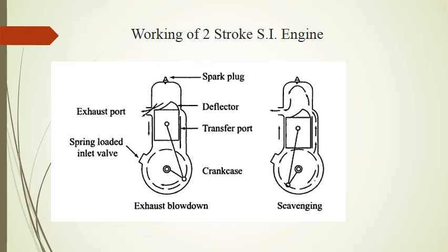During the upward motion of the piston from bottom dead center, the transfer ports and then the exhaust ports close, and the compression of the charge begins and the cycle is repeated.